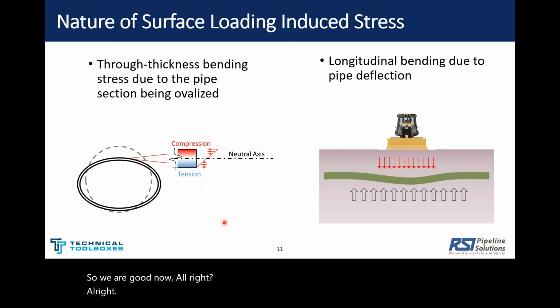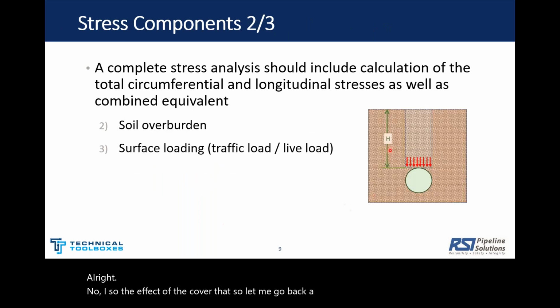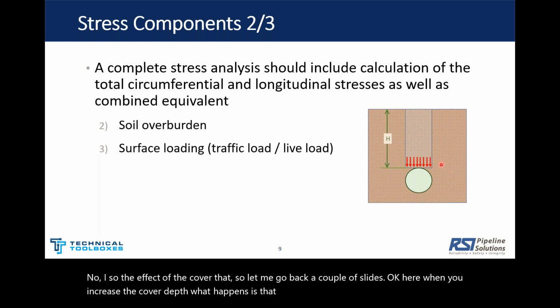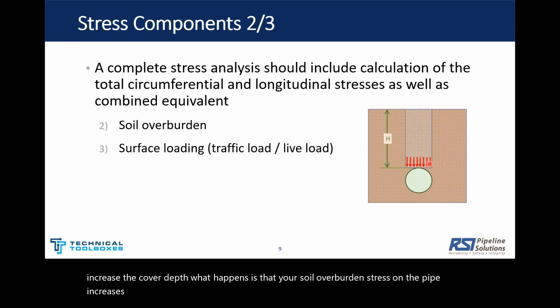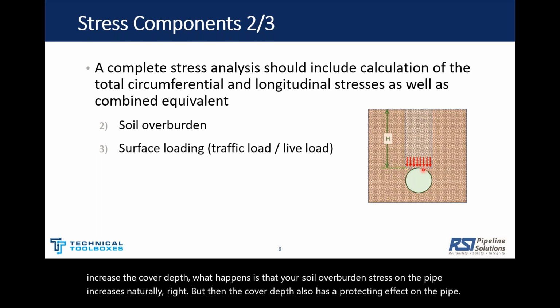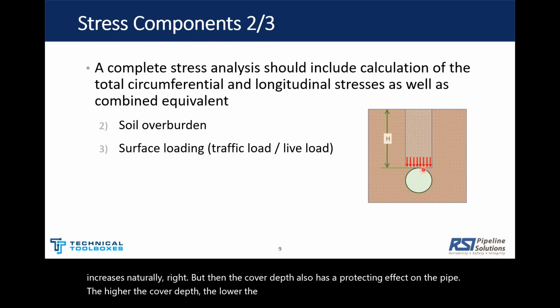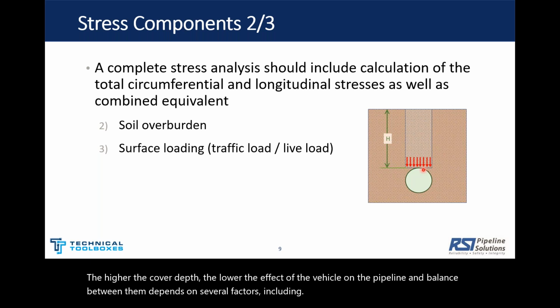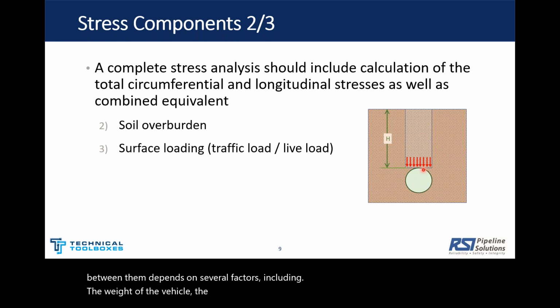No. So the effect of the cover depth. Let me go back a couple of slides. Okay, here. When you increase the cover depth, your soil overburden stress on the pipe increases naturally, right? But the cover depth also has a protecting effect on the pipe. The higher the cover depth, the lower the effect of the vehicle on the pipeline. The balance between them depends on several factors, including the weight of the vehicle, the unit weight of the soil, and burial depth.